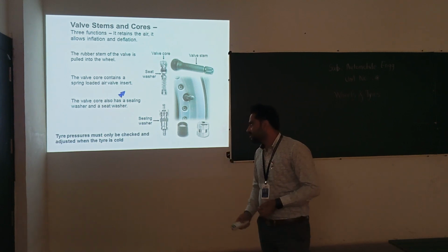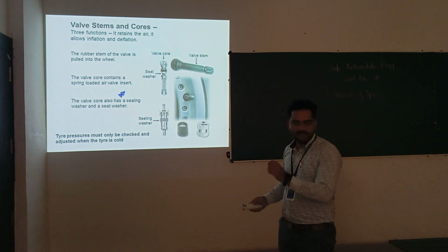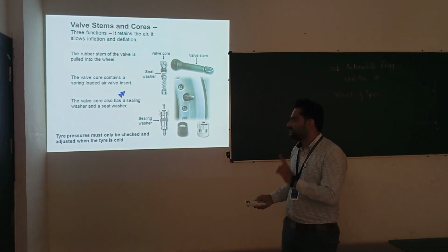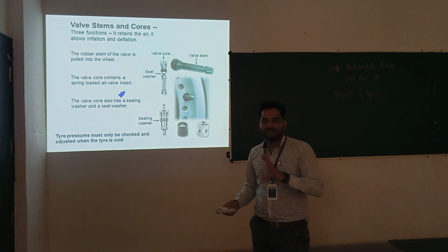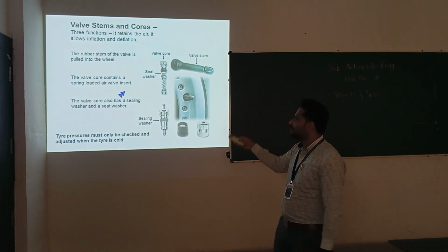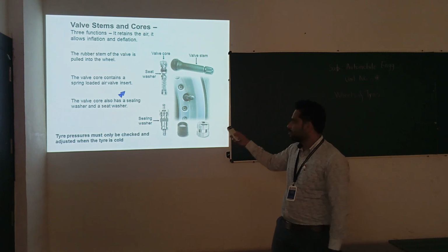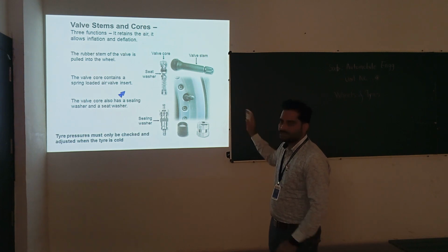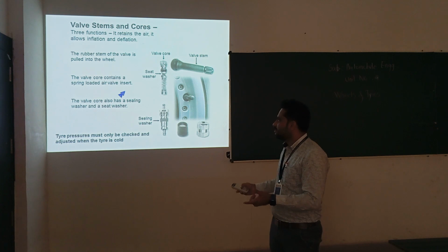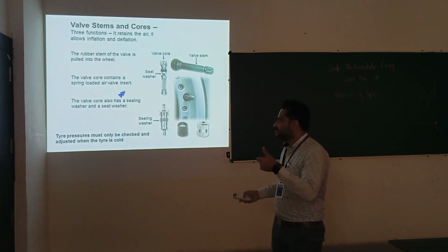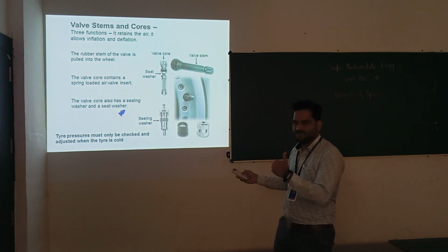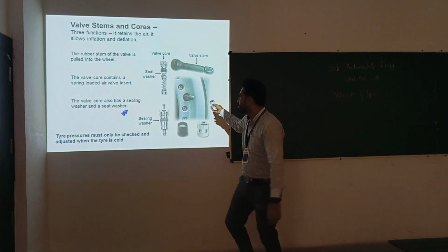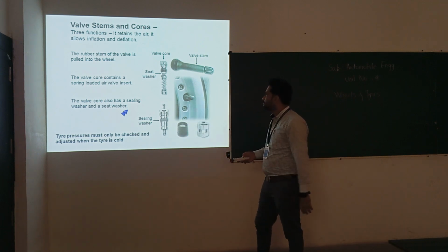Tire pressure: there is one note. The tire pressure must be checked and adjusted when the tire is in cold condition. Okay. So this is about the valve stems and cores, and how the construction of the valve takes place. There is a seat washer, there is a sealing washer, and there is a cap to avoid dust getting inserted inside the valve. Okay. Next one.